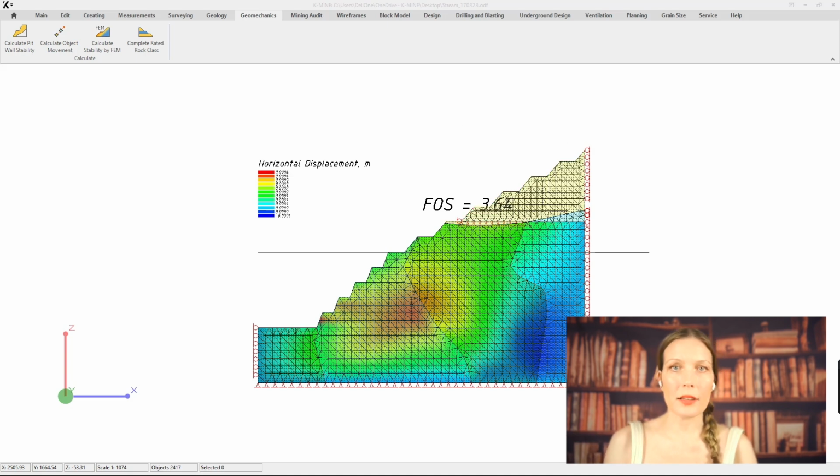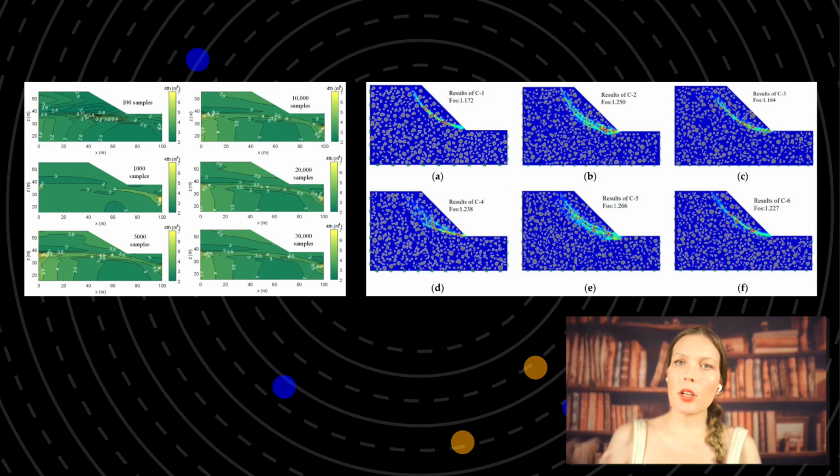In addition to static calculations, specific external factors often need to be accounted for. In seismic regions, slope stability is evaluated under earthquake conditions using pseudostatic methods, typically by applying an equivalent horizontal acceleration. Rainfall or climate factors also play a role. Prolonged precipitation, for example, can saturate slopes and reduce soil strength, so analysis must include moisture sensitivity.